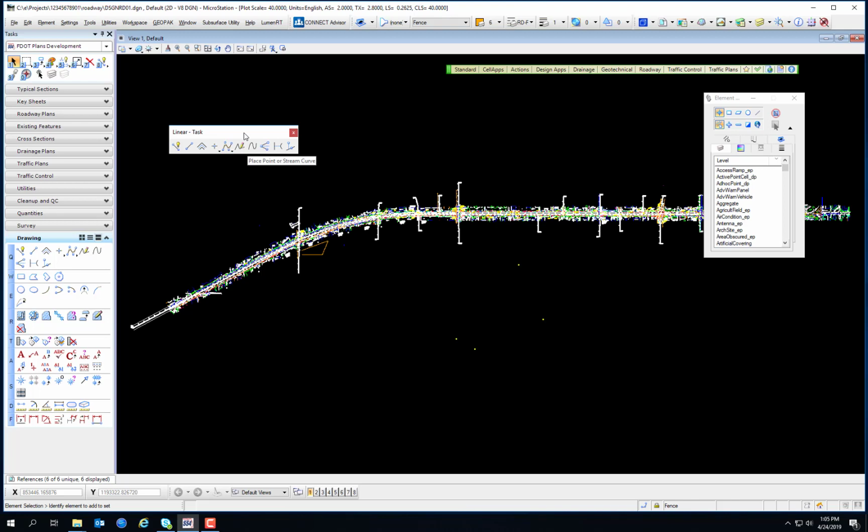The Create Curves task is used to draw curves and exact isoparametric lines from a solid or B-spline surface. We won't necessarily be covering these three tools very much, as well as the Place Streamline string, which is used to place a streamline string primarily for tracing images when digitizing. I used this some when I traced a bunch of images to create the MUTCD cell library.